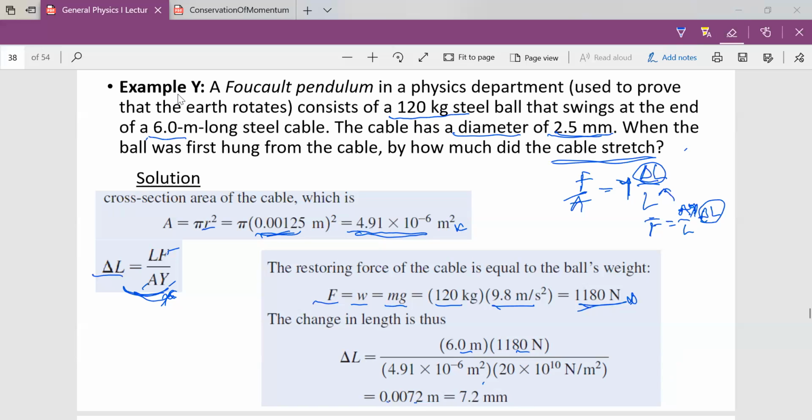Always confirm these values, okay? Use your calculator to punch it. Sometimes they vary. So just to be sure you are punching the right way, and you get used to the way your calculator works as well. So we've seen how we have used the Young modulus equation to obtain the stretch for a rigid body. So these questions can actually be varied. We supply a different parameter. We can ask you to find the Y, we can ask you to find L, we can ask you to find the force. Depending on the parameters that are given, you will know the approach to take, okay?